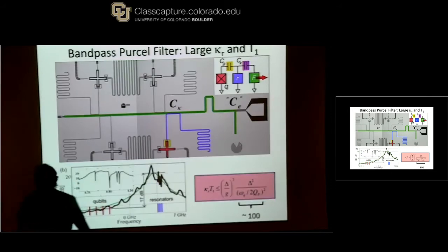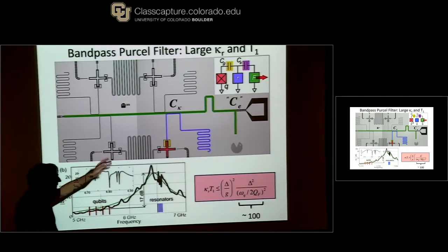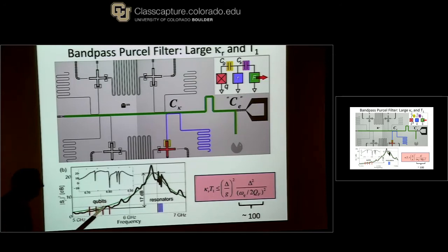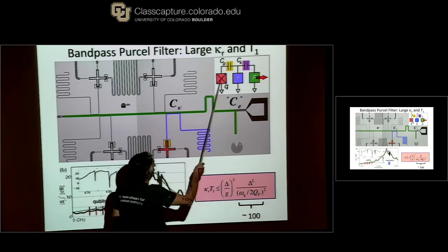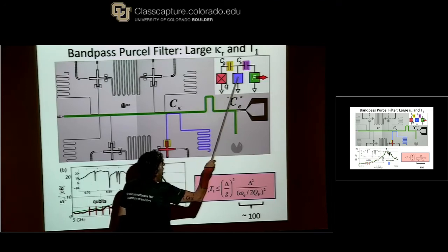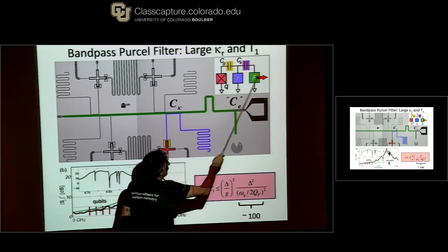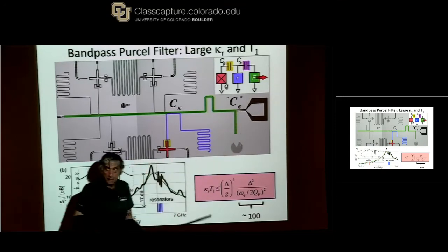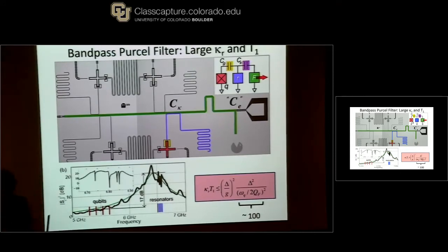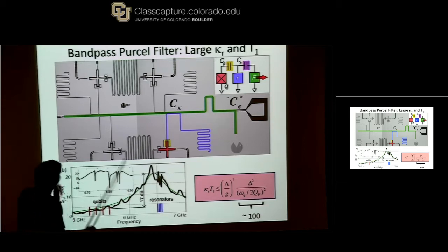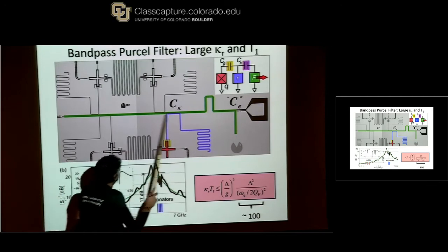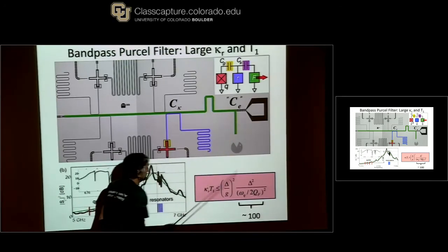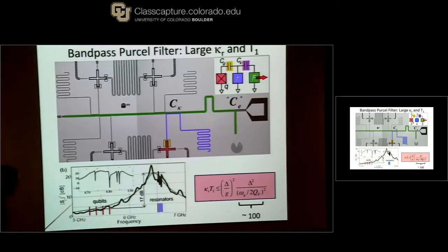And it turns out, thinking about that circuit and what we did here, there's a very simple way to fix that: besides having the qubit connect to a resonator, you connect to a second resonator before you read it out, to act as a filter. So the one resonator is kind of a one-pole filter to filter out the measurement from the qubit separately from damping of it, and then we just put in a second filter to do it even better. So this second filter, in fact, in this structure here, is this line right here, and forms a second low Q resonance.